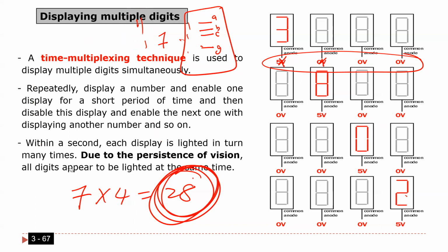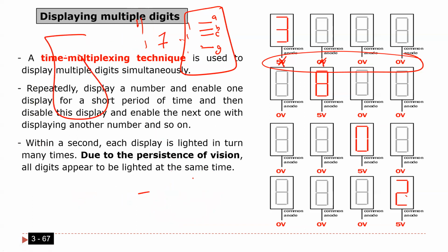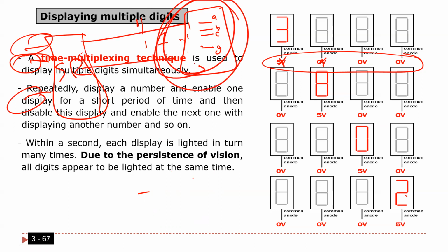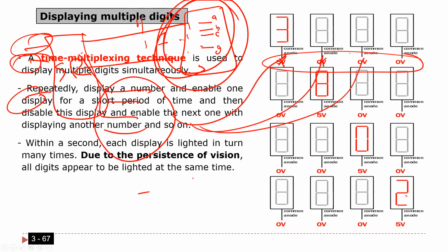By using a shift register. So here I'm going to use a shift register, and similar to what we did before, we need only 3 pins. For the output of the shift register, we need 7. This 7 is going to be connected to everybody. We need 4. These 4 are going to be connected to here. You understand what I'm saying? And this is how the 7 segments are connected here in this port. It's very interesting.